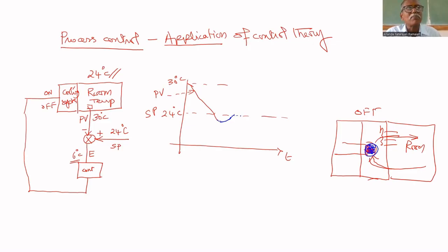There will be a further increase in temperature, because you cannot expect it immediately. Two reasons. One is, as he said, the element temperature does not immediately come to low temperature. It takes some time. Another reason is the sensor is here and the cooling air is coming here, so it has to circulate this much distance. Till then the room will get heat from all sides, but from only one place it is getting cool air. Are you able to understand? That's why there will be a further increase in temperature.